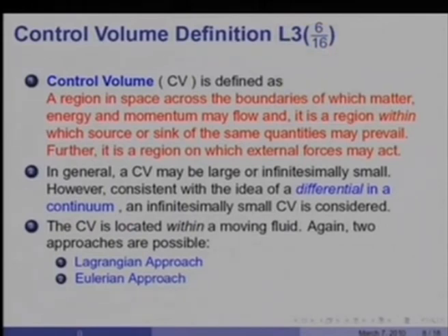I said in the continuum approach, the fundamental laws are applied to a fluid element we call a control volume. So, let us define the control volume. The control volume is a region in space across the boundaries of which matter, energy and momentum may flow, and it is a region within which a source or sink of the same quantities may prevail. Further, it is a region on which external forces may act.